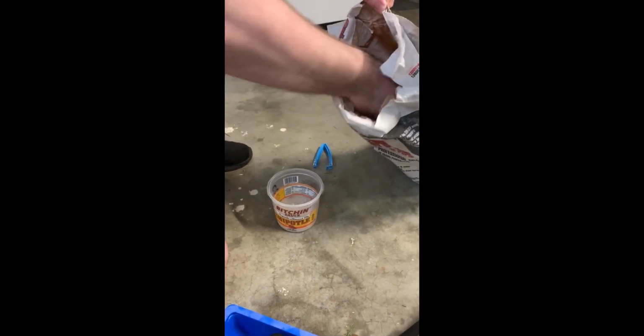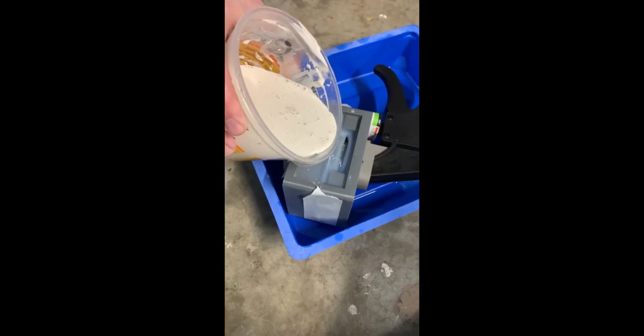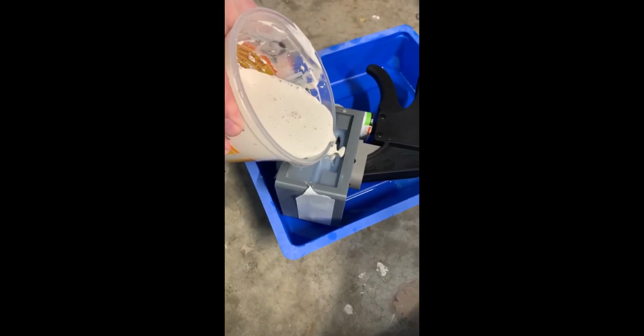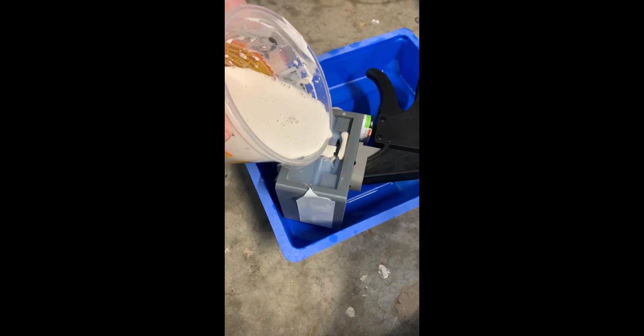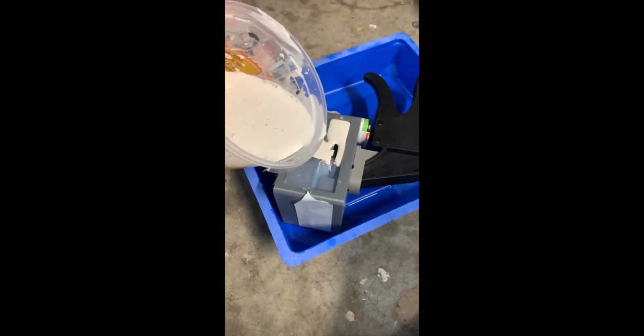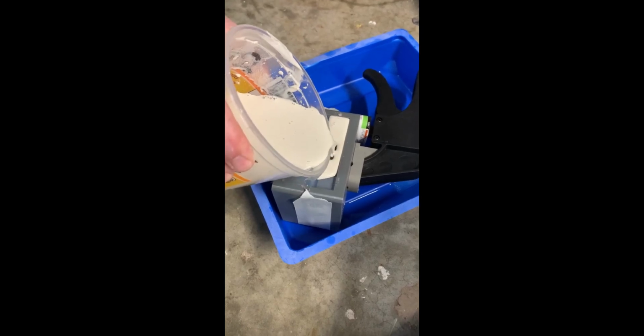But you can see I did get a reasonable casting when I took the top off, although it broke when I went to remove it. That's because I used way too much water in the plaster. I'm actually surprised that it set up at all. Now that does lead me into the last thing that I want to mention, which is about sprues and risers.